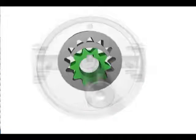The drive gear, which has fewer teeth than the ring gear, sits offset in the ring gear. This creates an open cavity between the two gears. The crescent seal, which is machined into the housing, divides this cavity, creating a positive seal between the inlet and the outlet side of the pump.